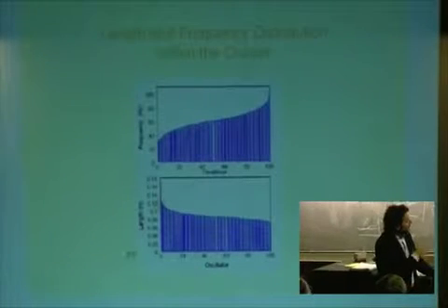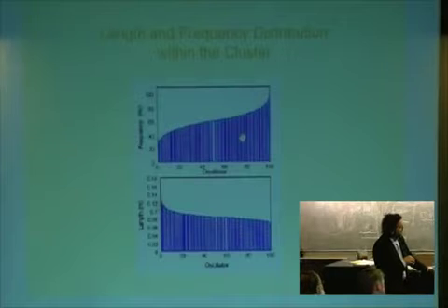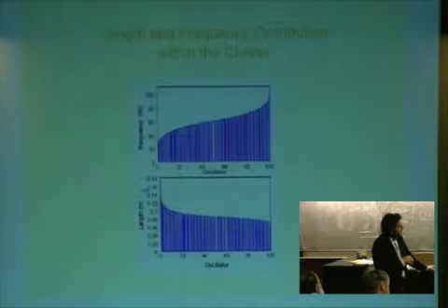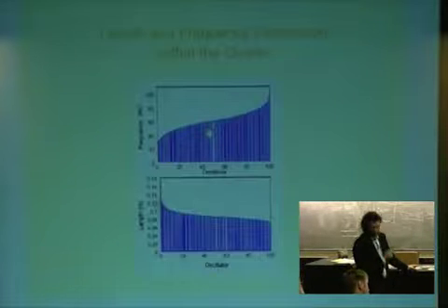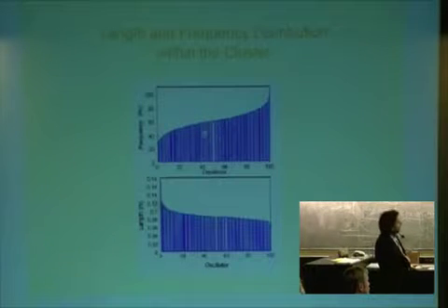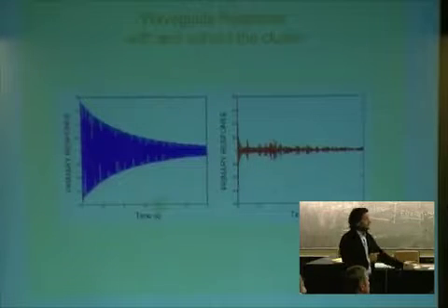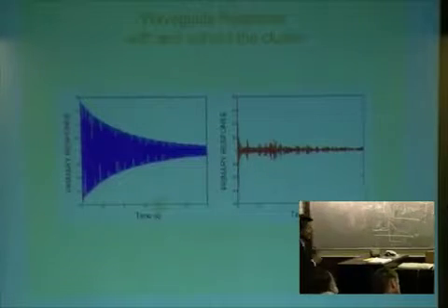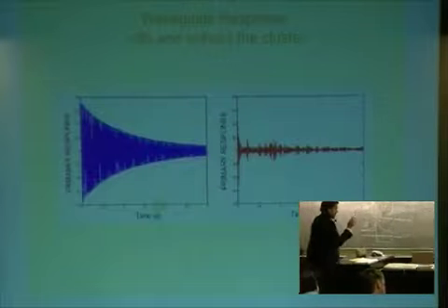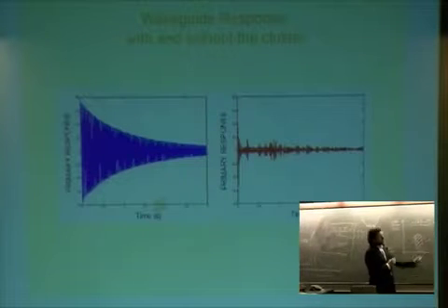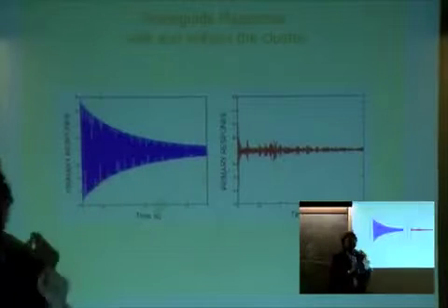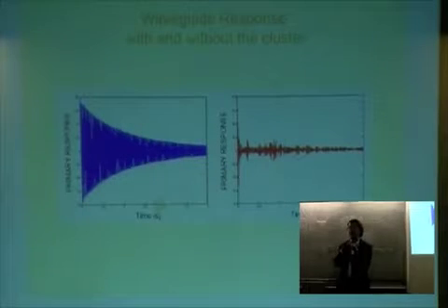These are the frequencies that we selected for the 100 oscillators, and these are the corresponding lengths. These are the frequencies that are computed on the basis of the optimal variational problem that we solved. Then this is the experimental comparison, by a laser beam, between the two. This is the response decay in the absence of the mini beams.